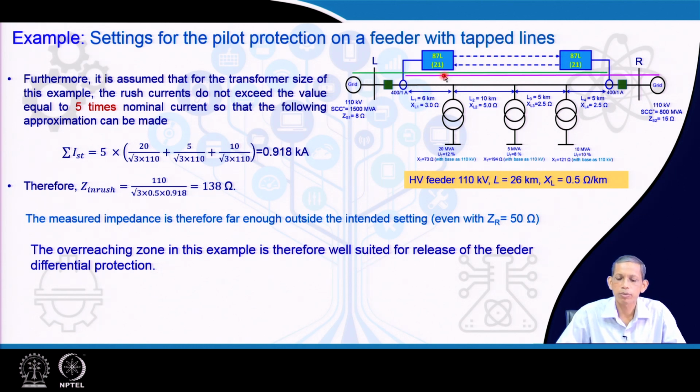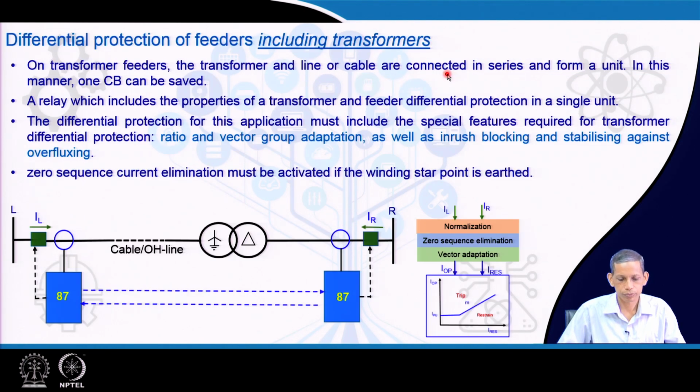So, it means that it supplements the corresponding differential protection in a better way. We would like to say here that for a tapped line, if the distance relay supplements the 87 L, that becomes a better performing differential protection, so that it becomes sensitive and reliable also.